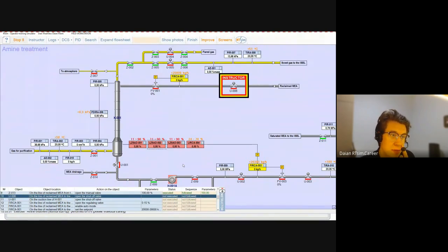I also didn't open the valve on the drain because we use the drain during shutdown. And we didn't open the manual valve Z7 because this is a pipe to the atmosphere. We also need it mainly during cleaning and shutdown, because there is no feedstock in the column.